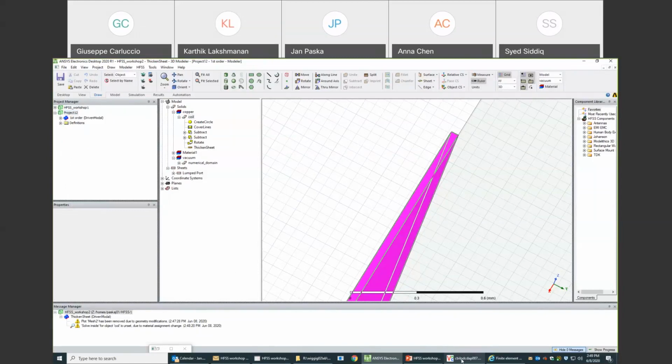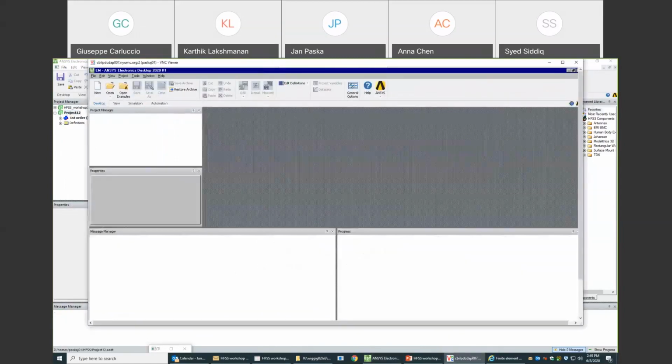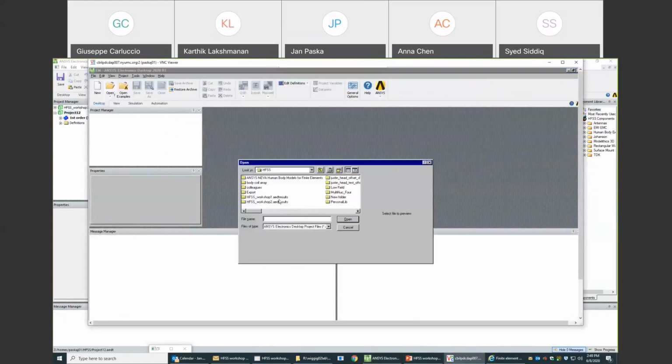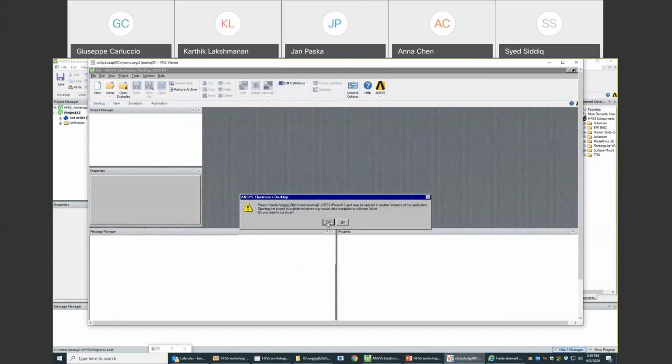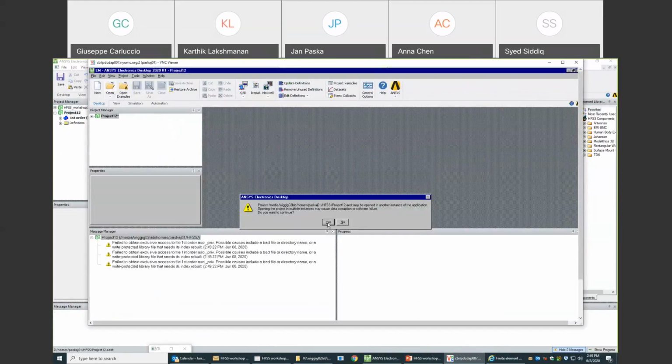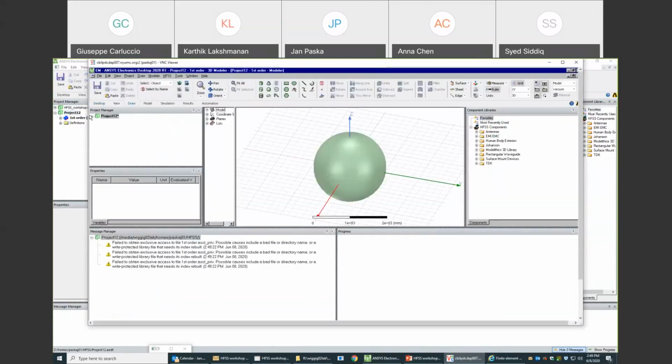So with regards to this point where you gave copper, don't you need to give it a conductivity? In the boundaries, doesn't it need to show a finite conductivity, or is the way you did it fine after thickening the sheet?